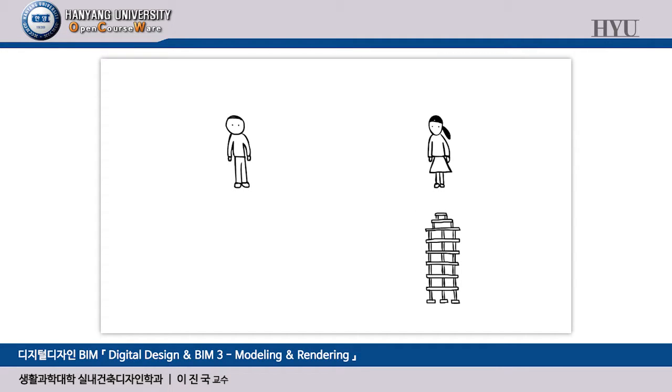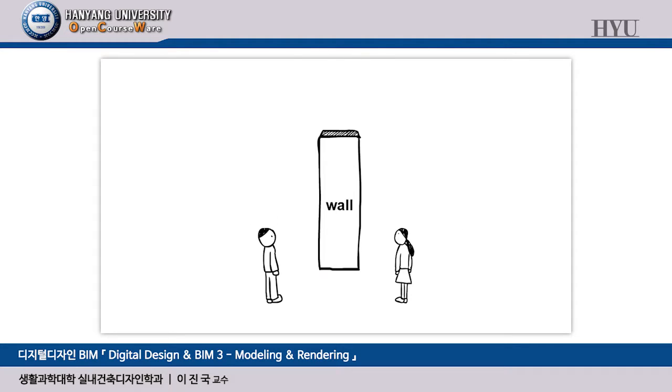Now that we've managed to get the appropriate part of Joe's model over to Martha, is she able to start her part yet? More often than not, the architectural logic of the BIM model doesn't 100% match the structural logic. For instance, columns in the architectural model may be modeled as walls, but the engineer really needs columns there for a structural analysis. What we need here is workflow compatibility to ensure that element interpretation is correct, regardless of the differences between the parties.